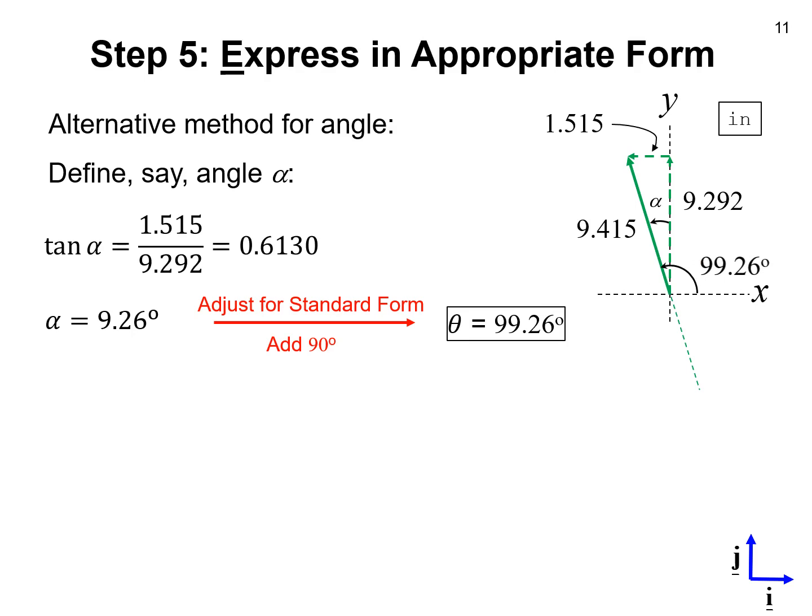And so notice here I'm adding 90. In the last question, I was adding 180. Don't just memorize a final addition. Just think about what each case is asking you to do. And in this case, I think it's clear that the alpha being measured from the y-axis is 90 degrees away from the x-axis plus the additional 9.26 degrees that you calculated.